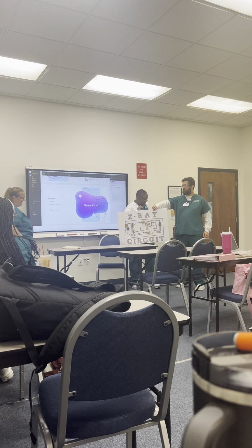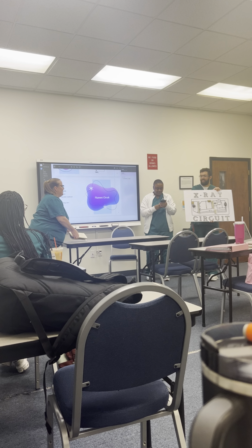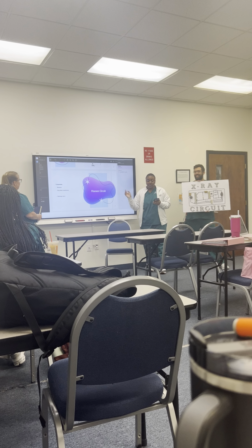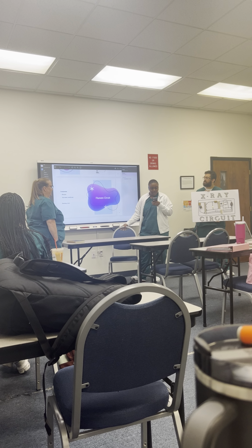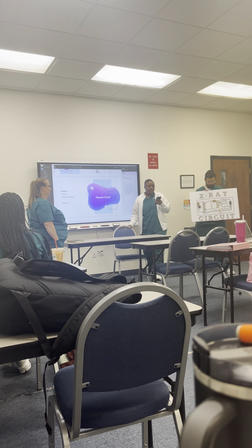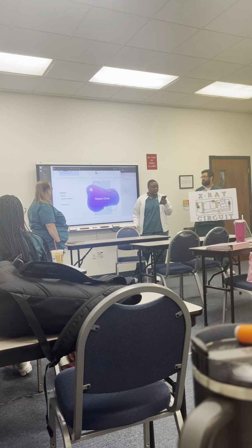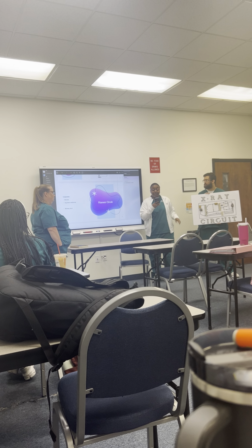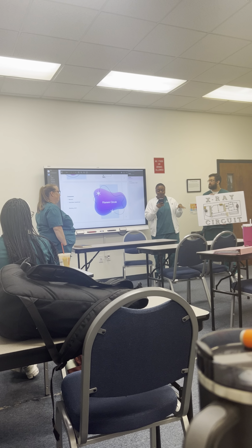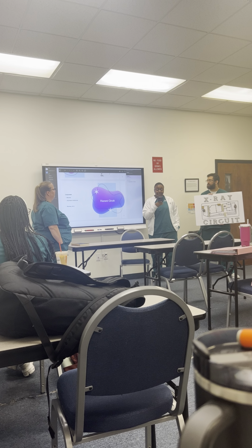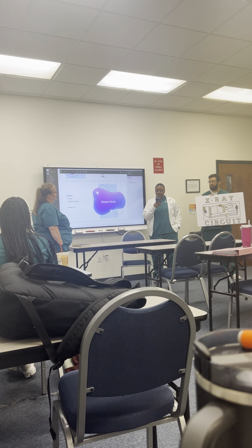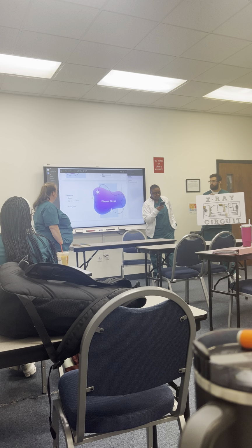I have the filament circuit. In the filament circuit, you have the rheostat and the step-down transformer. The rheostat is also known as the mA selector. It is controlled by the mA selector on the operating console, which directly determines the current that is applied to the selected filament and the number of electrons boiled off and available for X-ray production.